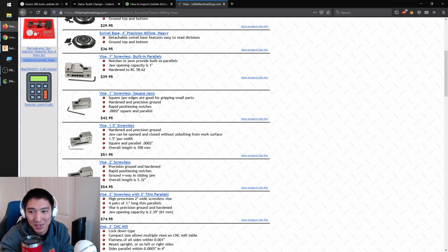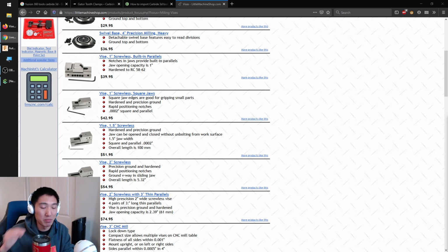Consistent onion skins. Toilet paper is getting scarce over here. Make sure you start with a level wasteboard, like machine surface it so that you know it's perfectly flat, and then maybe double-sided tape, and then just surface it down to about 4 thou or so.